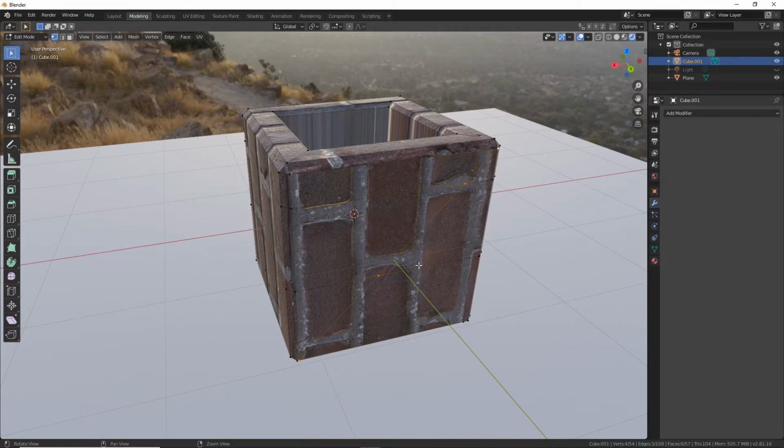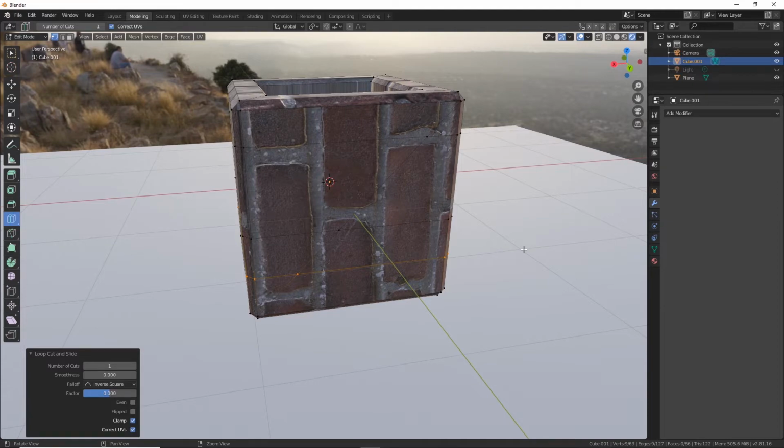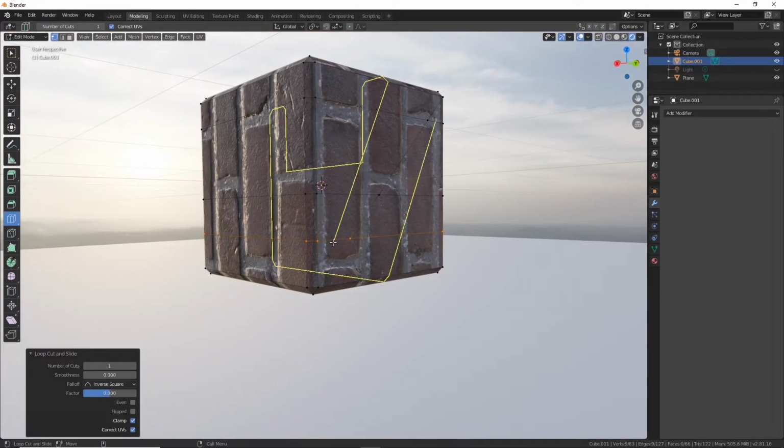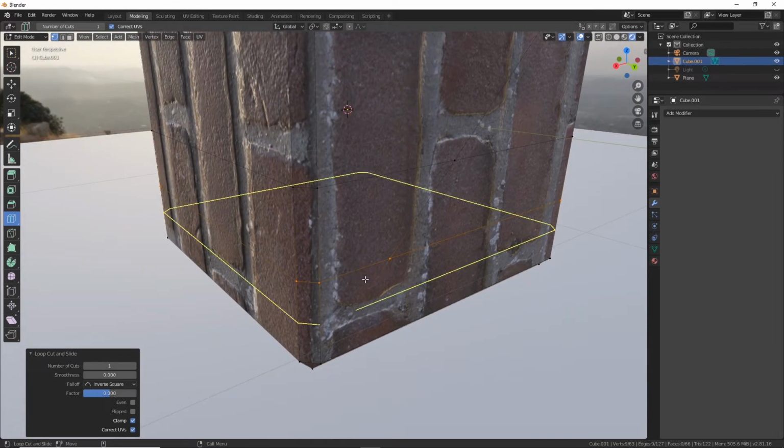I've just done that to break up the edge loop capability, because now here there's a triangle, and it doesn't understand how to draw an edge loop across triangles. So if I do an edge loop in the center, it's quads, so it can get through, but here it breaks. It still finished the edge loop, but it couldn't quite see.